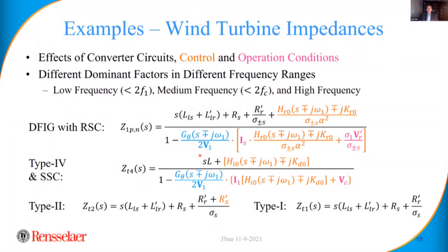So you really just have the numerator, the impedance that I explained before, right? However, when you're close to the fundamental, the phase lock loop introduces additional complexity. And that's where you have to be really careful with your design. Particularly if you have a potential resonance near the fundamental, then the design of the phase lock loop becomes really important. At higher frequency, above that 10, 20 hertz away from the fundamental, it's really dominated by current control.